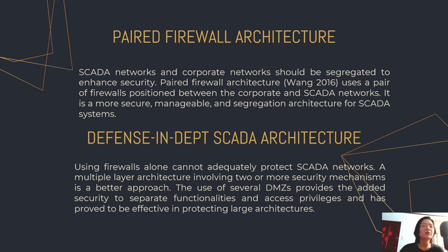Defense in-depth SCADA architecture. Using firewalls alone cannot adequately protect SCADA networks. A multiple-layer architecture involving two or more security mechanisms is a better approach. The use of several DMZs provides added security to separate functionalities and access privileges and has proved to be effective in protecting large architectures.